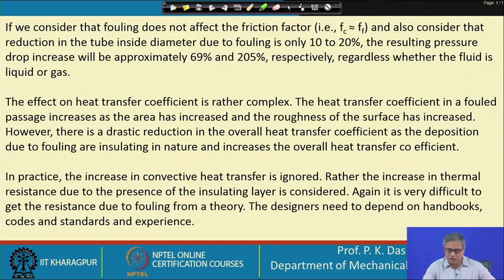So, if that is so, the designer needs to depend on handbooks, codes and standards, and many times on experience. Two things are there: how one can rate the performance of a heat exchanger in the presence of fouling, and how much extra area or extra surface or extra capacity of the heat exchanger is to be allowed in the design stage to allow for the deterioration due to fouling.